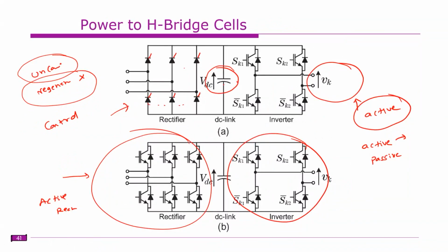So in that case, a significant amount of power is transferred from the load to the source, right? So to get that power, we must have a mechanism, or we must have a converter that can allow the power flow in both directions. So these thyristors will allow power in both directions. Therefore, it can have regeneration capability. Regeneration is possible.